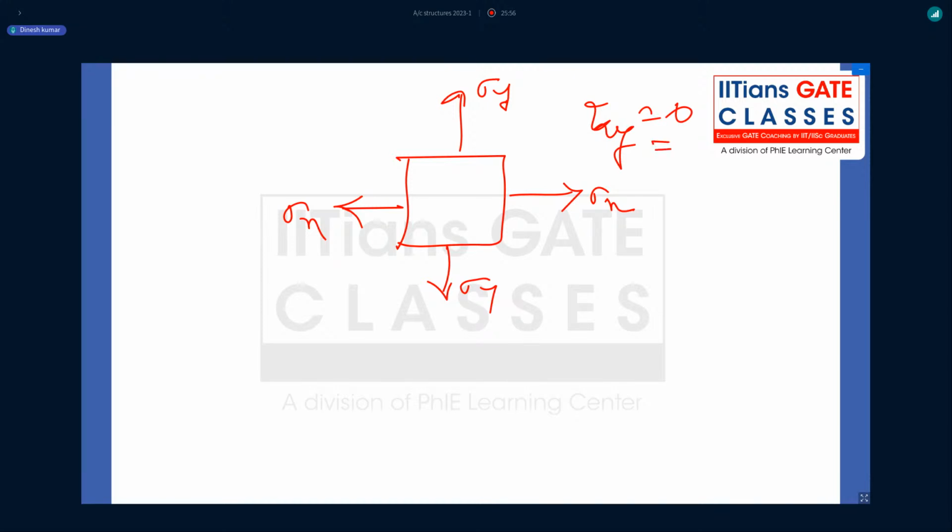Okay. So for all these cases, what are the things you should know? What are my stresses in an inclined plane, like sigma s, sigma t? Then what are my principal stresses sigma 1 and sigma 2? What are my principal planes theta 1 and theta 2? What is my tau max? What is the plane of tau max?